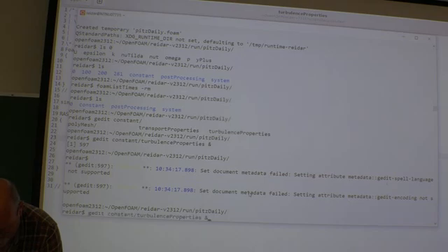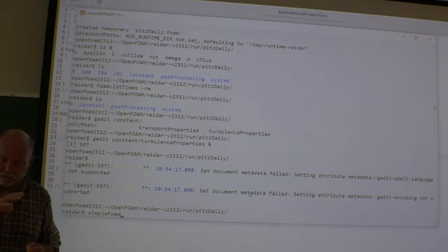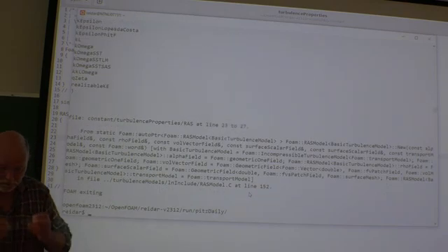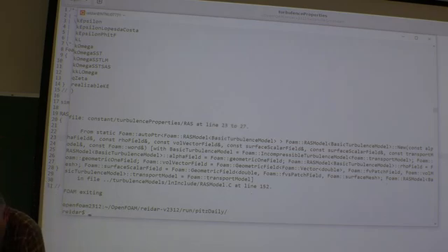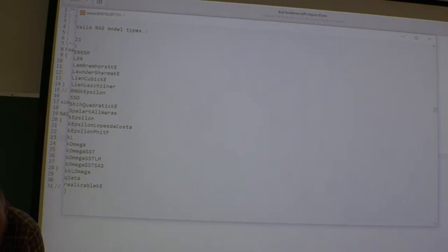So let's try that one. Simple form. I don't have to recreate the mesh. I only change the model. The mesh is the same. So yes, you get an error, total crash, and then you have a list of valid models. So this banana trick is quite nice in OpenFOAM. When you are wondering what's my options, write banana or some stupid word, and then you try to run it. It will crash, but hopefully then give you a list of possible entries that you can use. So yes, here I have 21 models.